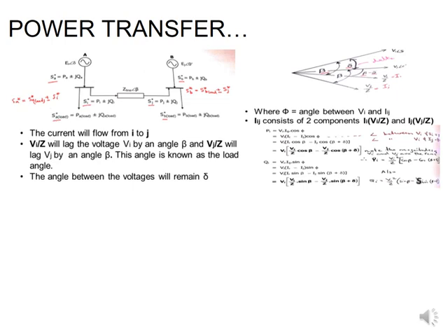Because I've said here that my magnitude is usually the same, as you will see as we go along, and I've written on the side as well in pen, my PI is VI squared over Z because my VJ and my VI are the same in magnitude. And then in brackets, I only have the cos beta minus the cos beta plus my displacement angle.